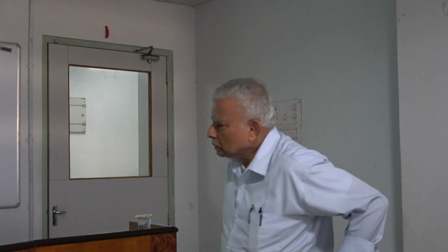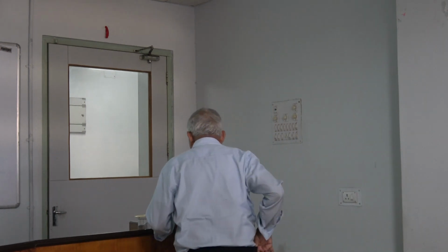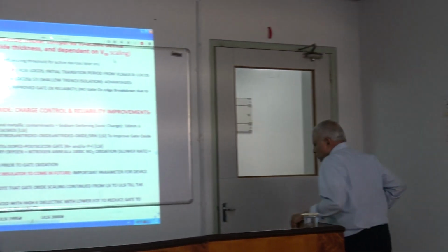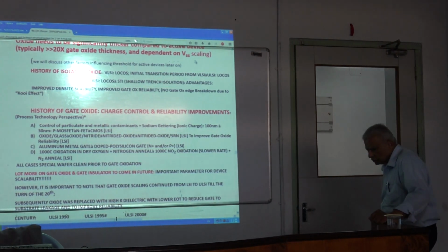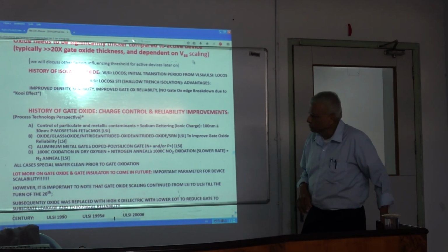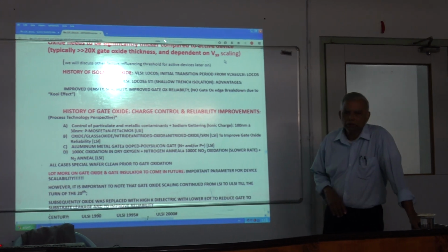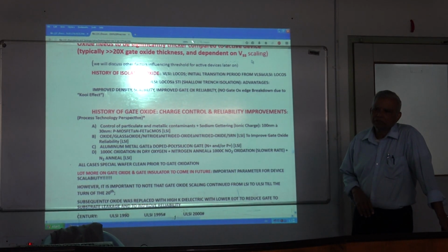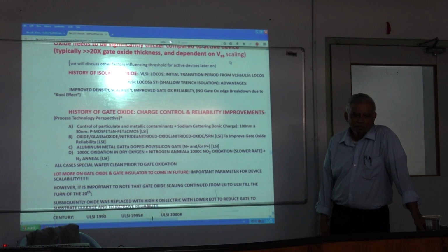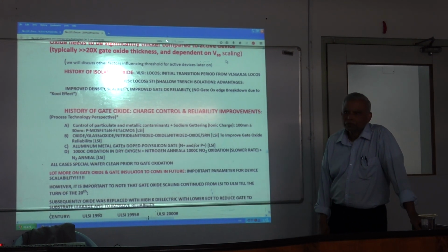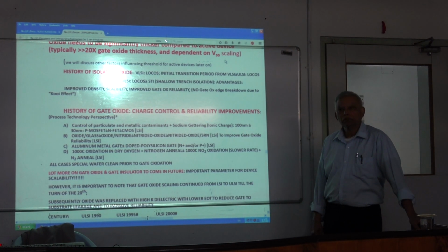And that gives leakage. So that's why you cannot use, for any real purpose as a field effect transistor, with any reliability, when oxide is thinner than roughly 40 angstroms for industrial purposes. So that's the limit of oxide.